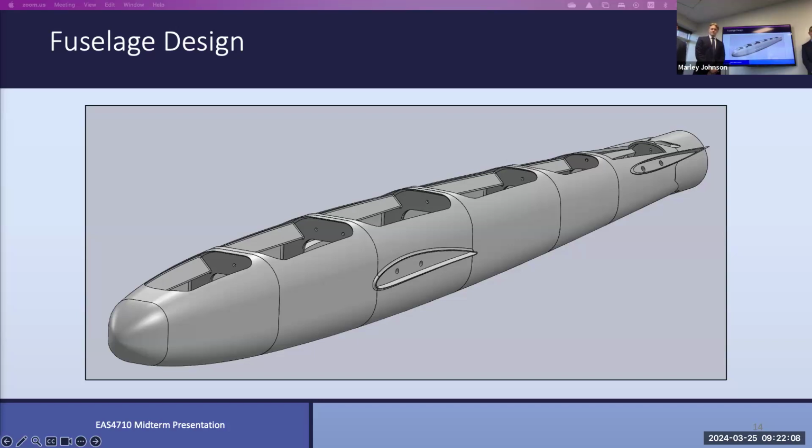Another problem is the weight, because you have more and more fasteners and metal. I don't think it's really necessary, and when you consider weight, I'm concerned about it because in the end it all adds up and your total aircraft weight may become a problem. Another concerning part about putting two fasteners right around the longerons is that you're doubling the fasteners.